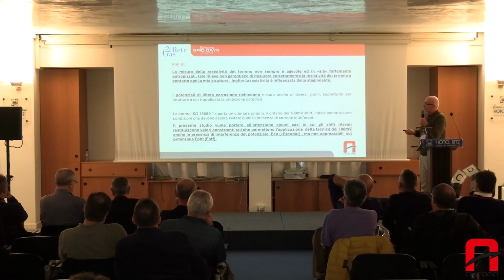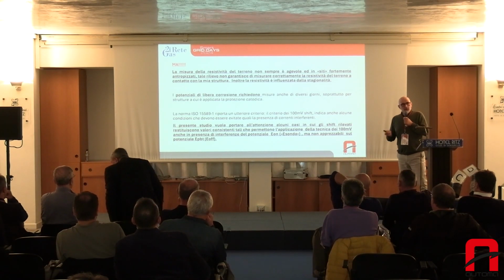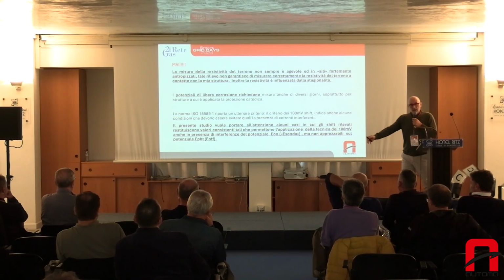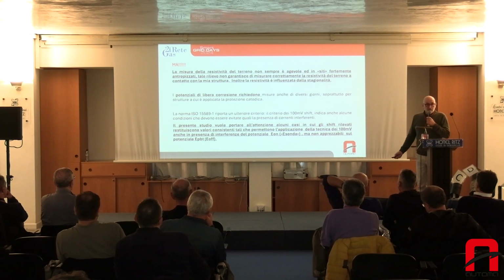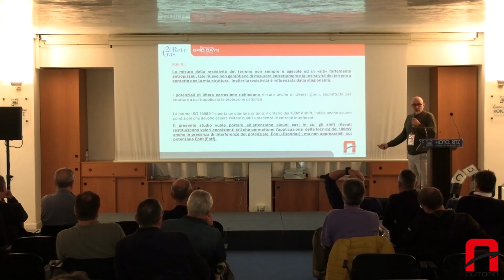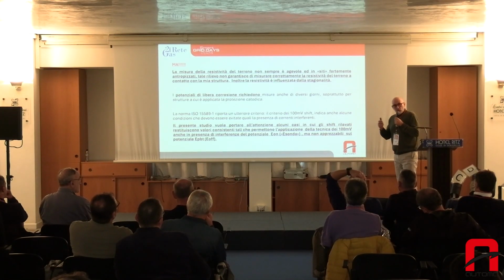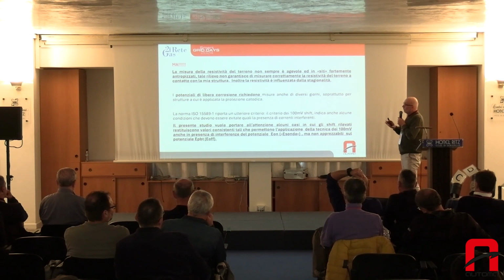Okay, so use resistivity, free corrosion. Well, but resistivity is not so easy to obtain as a figure. What should I measure? Because in a field, okay, I analyze 2-3 square meters of land. But in a city, everything is different. Within 10 meters, things can change very easily. So it's not so easy to have a very precise mapping.